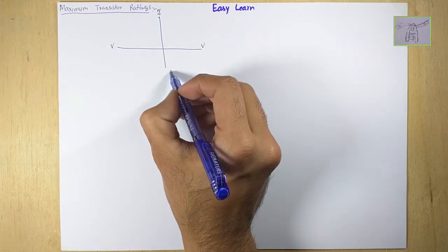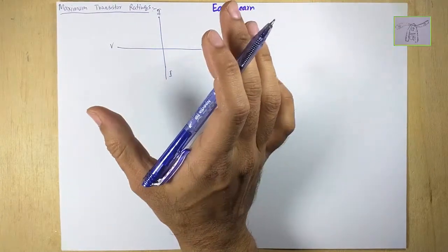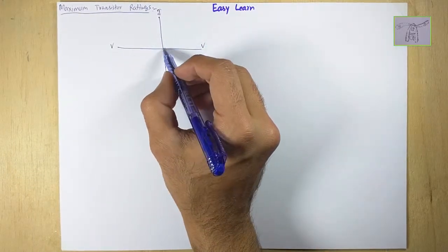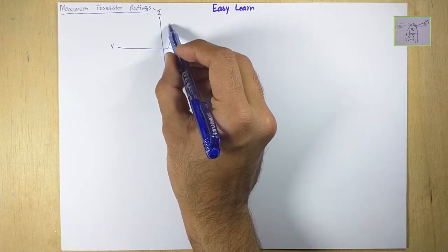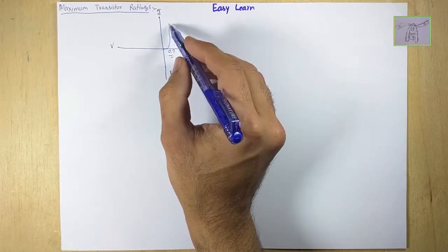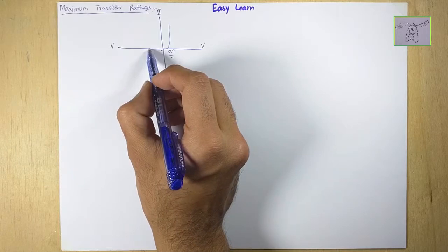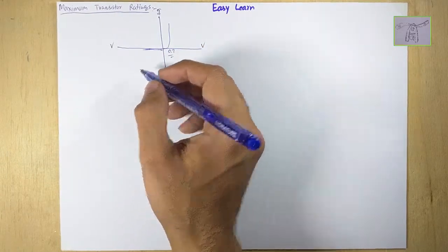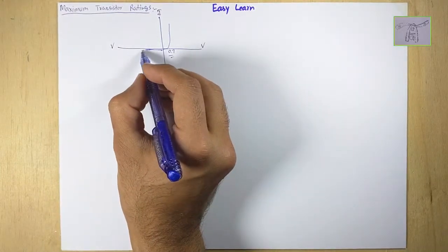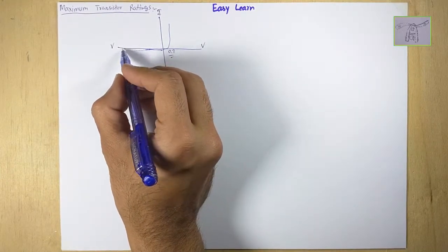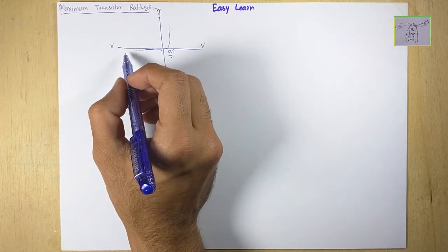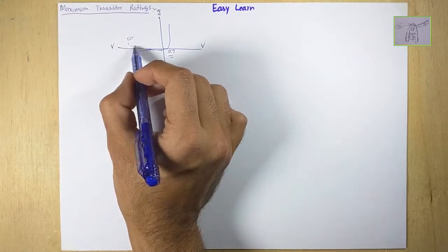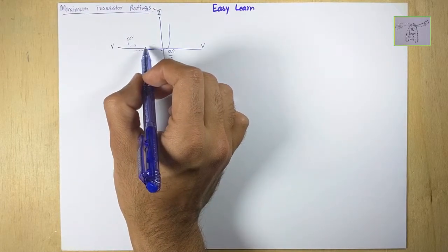For example, I already explained many times that its depletion region is exactly the same as the normal PN junction diode. If this is a normal PN junction diode, we approximately say 0.7 volt, and then it's okay. In reverse bias, it has to block all the current in the reverse direction. This is our expectation, but when we exceed this and apply a high voltage beyond its rating, for example, it is designed for 50 volts, and it is even recommended to stay 20% below the threshold voltage.